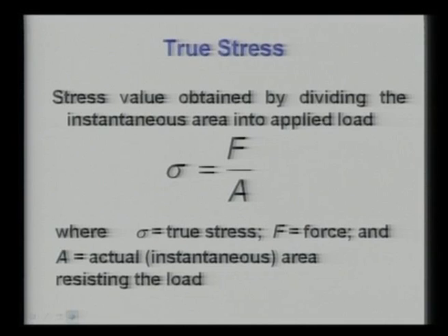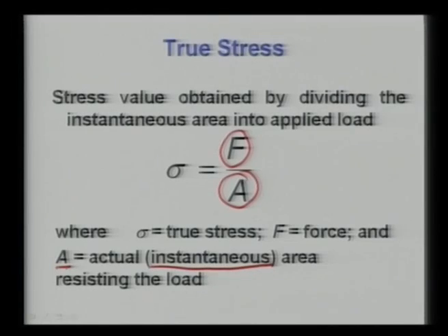Now how do you define the true stress? True stress is essentially force divided by the instantaneous cross sectional area. Instantaneous means at any given point of time, what is the cross sectional area of the metal specimen, that is known as the true stress of the material.